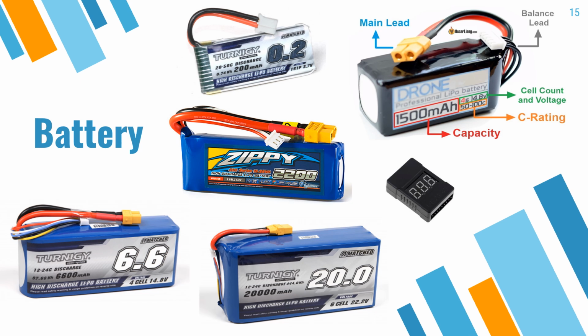There's also a C rating mentioned on the battery. If you multiply the C rating with the capacity, you obtain the maximum continuous current the battery can supply without getting internally damaged. Sometimes a second C rating is mentioned. If you multiply this C rating with the capacity, you obtain a peak current the battery can supply. And a peak current can be supplied for around 10 seconds before the battery gets internally damaged.